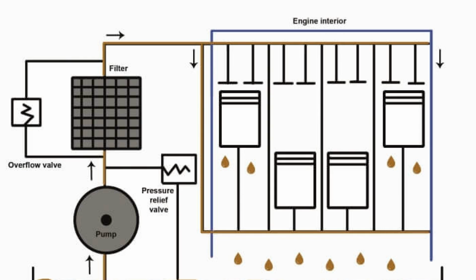A drop in pressure can indicate these troubles. The oil filter is severely clogged and needs immediate replacement. The pressure reducing valve is broken. The oil pump is not functioning as it should. Insufficient oil level. The oil pressure sensor is lying. Since the elimination of most of these malfunctions requires partial disassembly of the motor, such repairs are better to do with sufficient experience and knowledge.